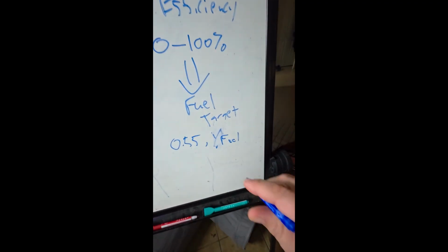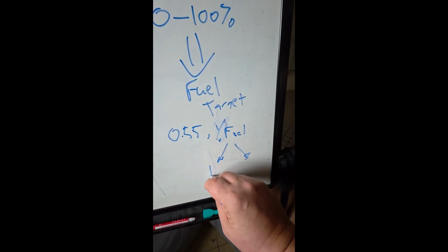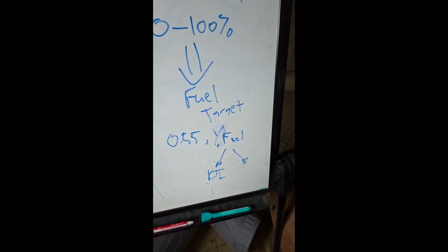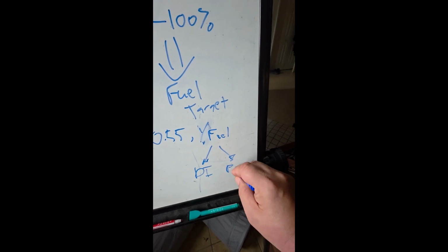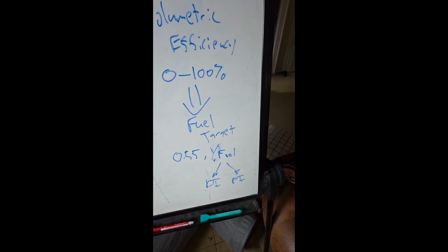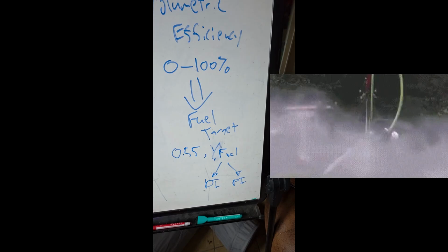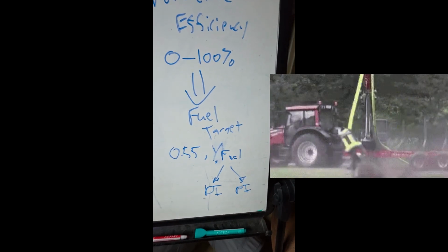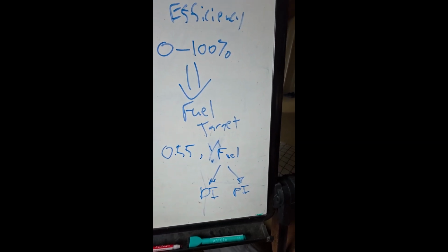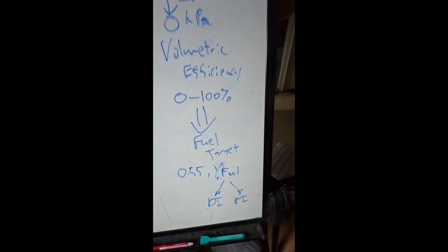And you learn later on that this is actually broken out into two factors as well. There's the fuel I direct inject and the fuel I port inject. And with port injection, you can send massive puddles of fuel into the system to be made available. The direct injection, though, is the injectors under high pressure. That is the superfine mist.